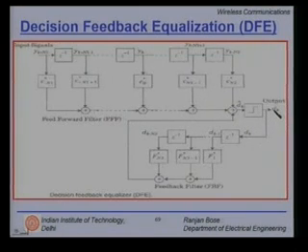But what is interesting is, for the first time we take this decision after the decision device and feed it back to the feedback filter FBF shown here. Again, this has several delay elements and then the feedback filter coefficients F1 star and so on and so forth, adding up.